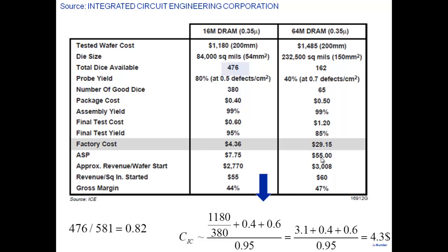But my point is that if you try to make it larger, the cost of the die increases for 2 reasons. One is it's occupying more silicon, and there's a fixed wafer cost. So when you occupy more silicon, the cost of that particular die increases. The other one is that the yield goes down, which also makes it higher here.